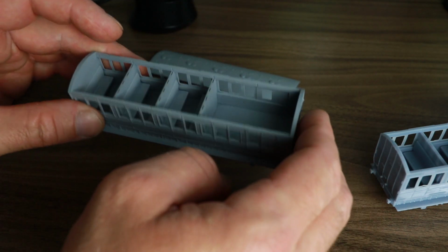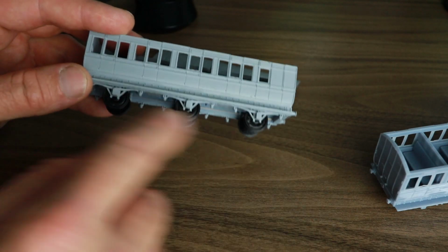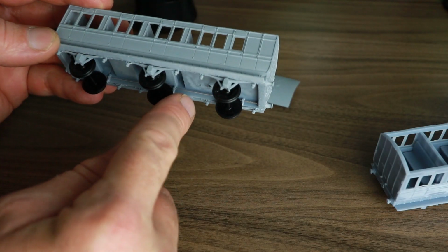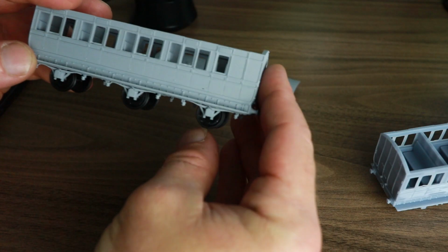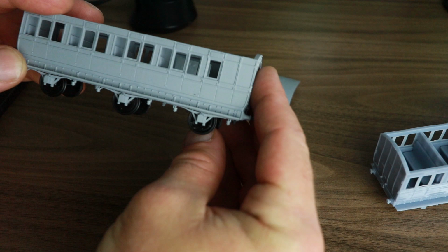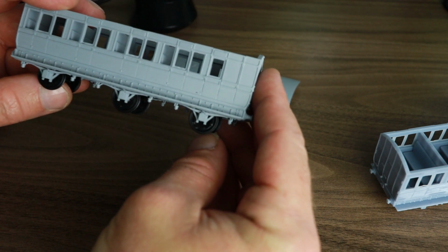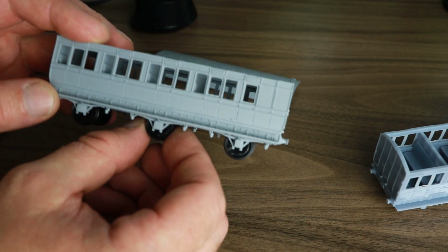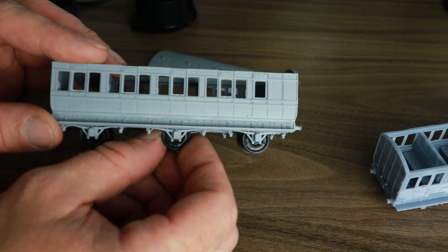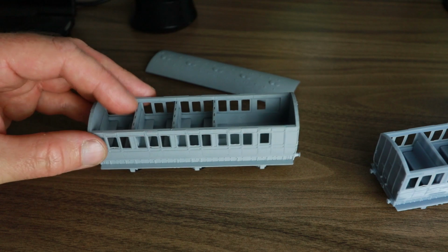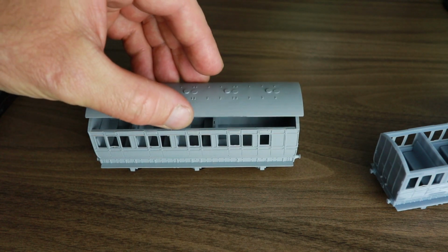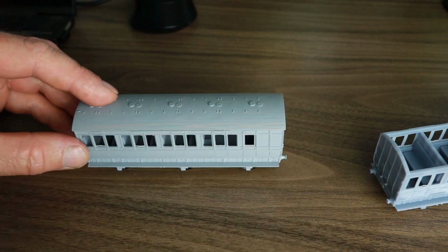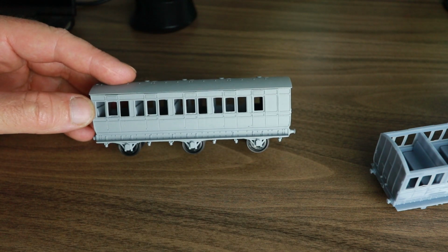But if we have a look at the underframe, you can see I've put some wheel sets in, and you might be able to pick up, we've got spring wires in here as well. So these wheel sets are all sprung, which is quite nice. We've got a little bit of end float on the centre axle just to help it go around corners. Anyway, there we go. That's a 3D printed railway carriage, and I hope you've enjoyed learning a little bit about how I go about producing such a thing.